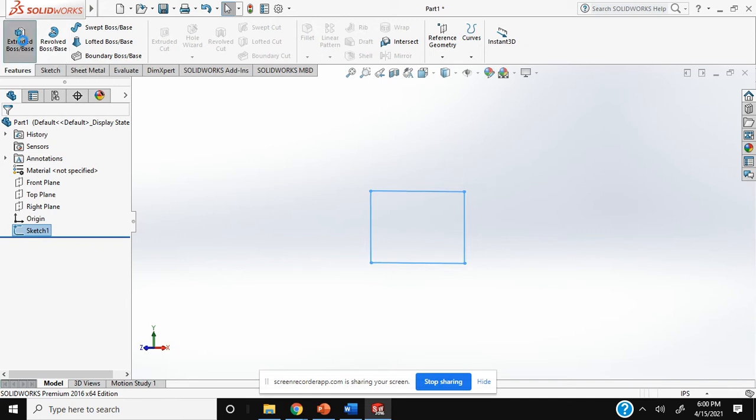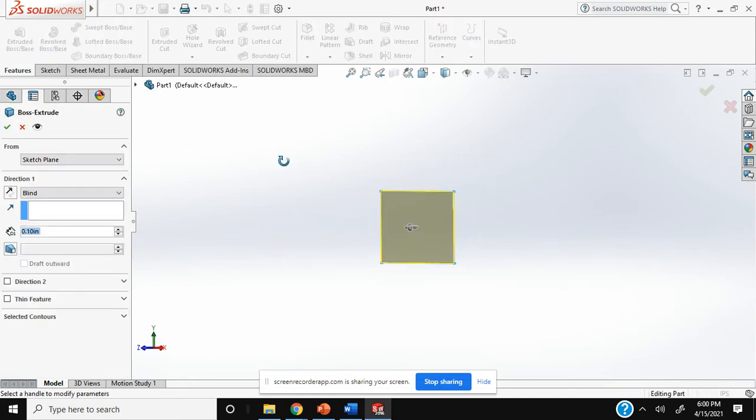So look here. I want to click extrude. Every time I change the value here, for example to 10, everything is gonna extrude. If I don't want it to go to this side, I'm just gonna change the direction, and it goes to the other side. Here the required thickness is gonna be 50. So I'm gonna click 50. After I finish, I can click OK.